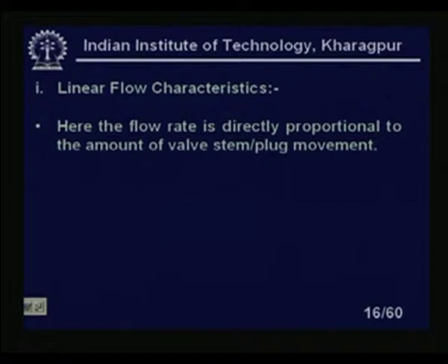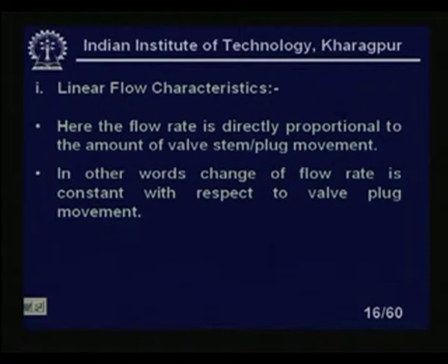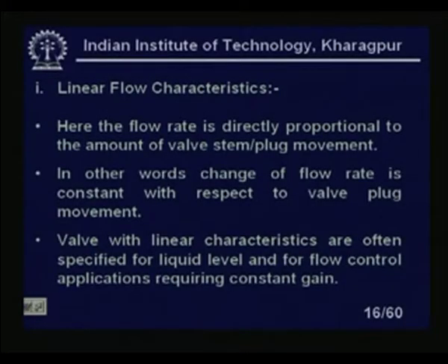Linear flow characteristics. Here the flow rate is directly proportional to the amount of valve stem plug movement. Okay, there is a direct relationship. It's linear. In other words, the change of flow rate is constant with respect to the valve plug movement. It is a linear curve. There is nothing too much to say. Valves with linear characteristics are often specified for liquid level and for flow control applications requiring constant gain. If you need constant gain, in that type of situation, I need this type of linear characteristics.